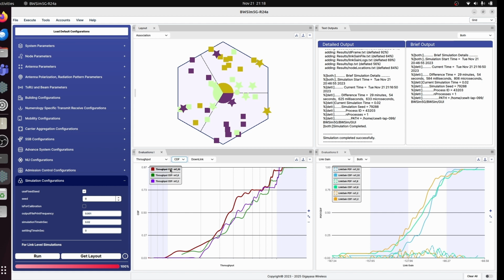That is where we have to understand that while we changed the number of RF chains, we made the number of antennas remain the same. So what exactly is happening is we reduce the ability of the antennas to give a strong beam that is traveling the entire way it was intended to travel, thereby causing this issue. Say, if you have a larger number of antennas, checked for 32, 8 and 2, you would get a result which resembles the rational line of thought that was discussed earlier. Now that this phase is over, let us move on to the next one, where for a constant number of RF chains, we'll be checking out three different numbers of antennas.